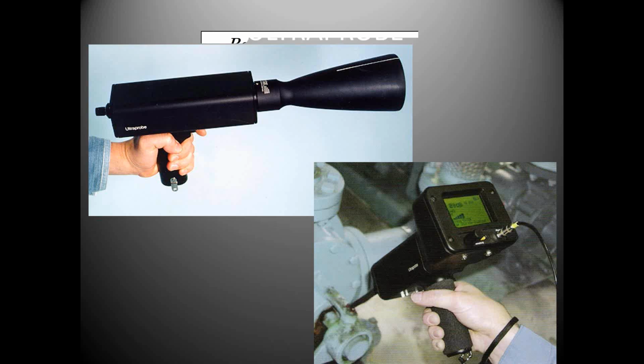The bottom probe is the Ultrasound 10,000, and like I say, they make a 15,000. You just change the tool on the end, and now we're listening to bearings. We can listen to the sounds of bearings as they wear. We can listen to the sounds of bearings as they need lubricant. And we can actually lube based on what this signal is telling us.